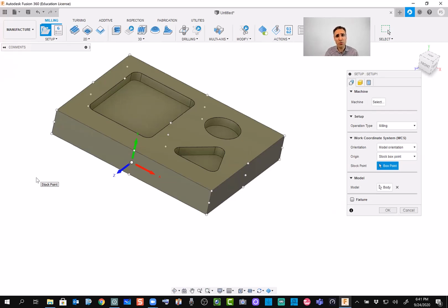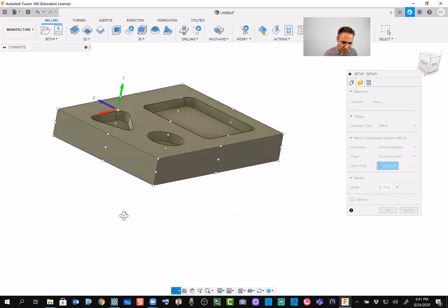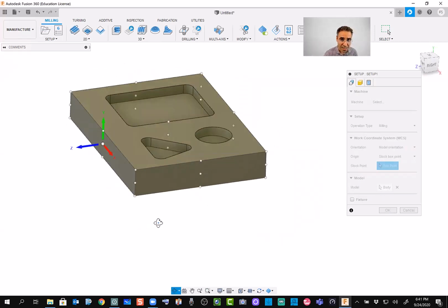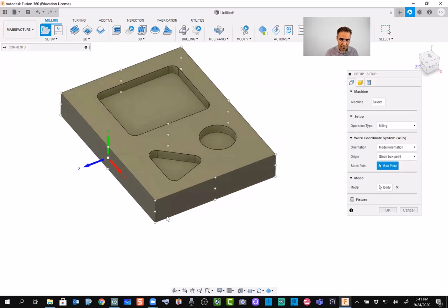So we need to tell the tool that this is the 0 point. It means that I need to select a point that later I can recognize as the 0 point. It's bad to have it at the center because we need to do measurement. It's very common to select one of these corners as the origin, because we know where it is. So how do we do that?